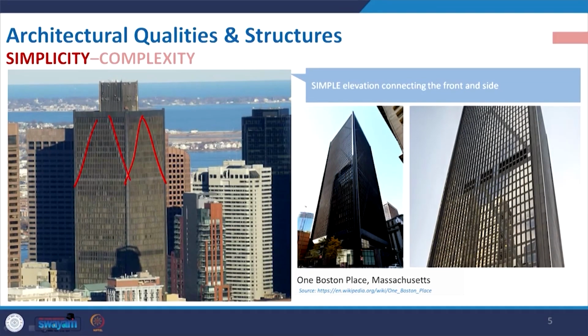Structural bracing is something where you have to resist lateral force. So, along with your members you go for supporting those elements with some cross braces. Depending on the floor, it is connected, and sometimes it is exposed externally, or sometimes it is not.